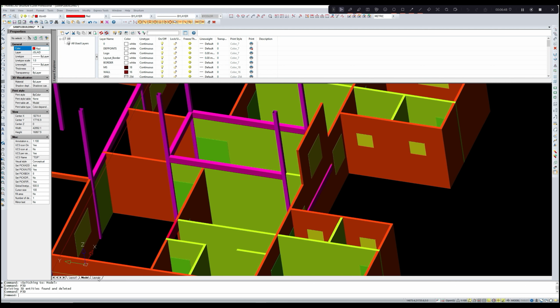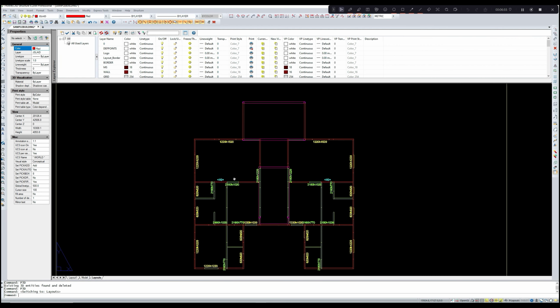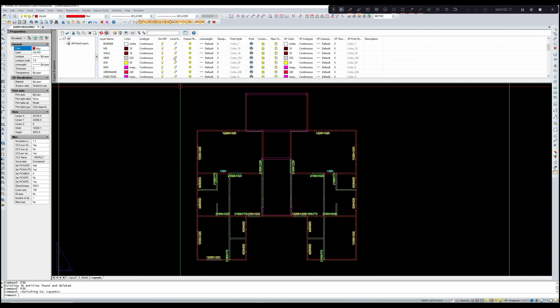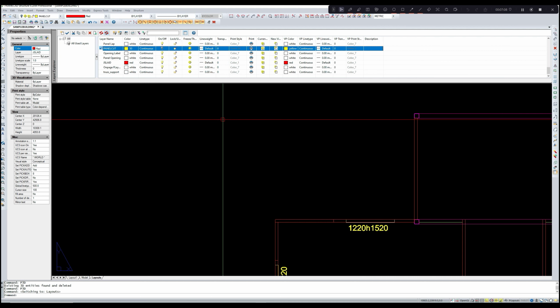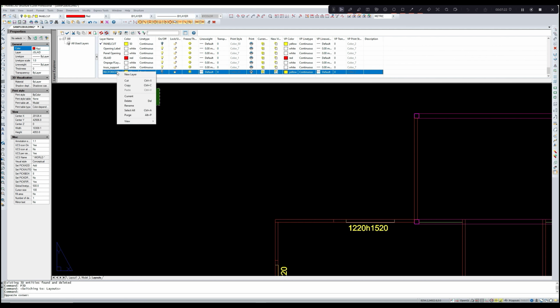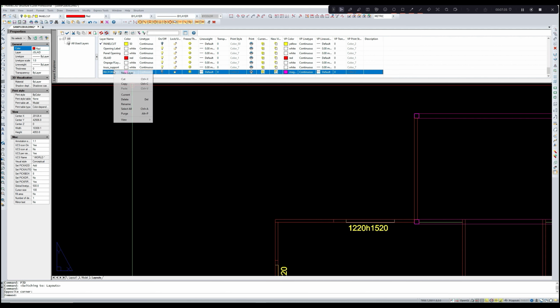generate the joist layout. To do that, you have to draw a few rectangles and some lines. So let us make a layer for rectangles for joist. New layer, rectangle for joist. Rename it joist. Let us make this color pink. Set it as the current layer.